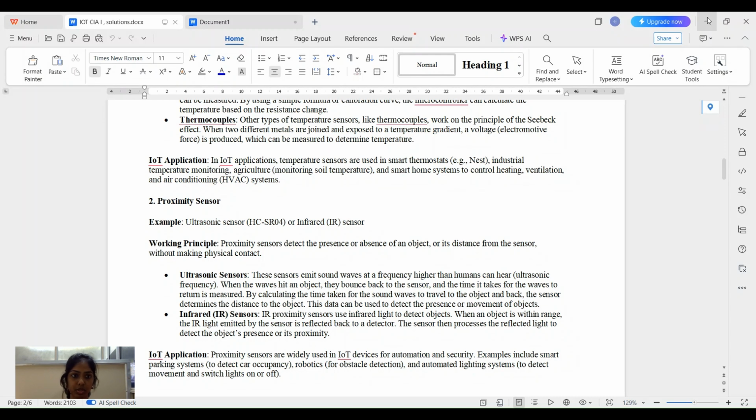So you just have to go to Tools, select Board, and choose whichever board you want. Then choose the port to which the board has been connected. Then go to File, go to Examples, and choose any one basic example. You can always start with the blinking LED: Basics, and then Blink. When you connect the Arduino to your laptop, you can try working on this.